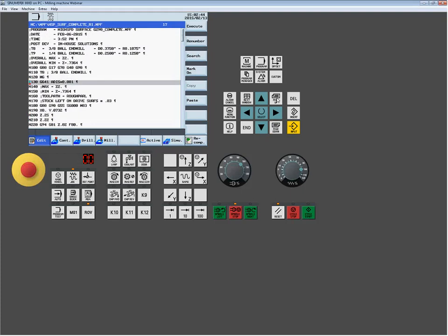Okay. So if I start to look at the program, I start to see a few different features. One of the first things I want to point out and show you, and you kind of saw this command a little earlier, is this G641 ADIST equals. Now what that is, that's actually a pretty old command. And that's the corner rounding function that I earlier talked about just in the last slide we looked at with the G645. G645 is just a newer version of this function.